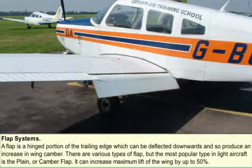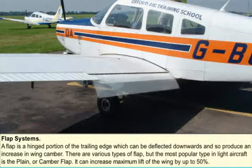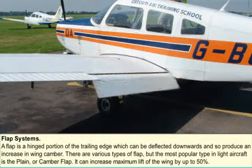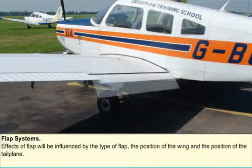The most popular type of flap used on light aircraft is the plane or camber flap. This type of flap increases the camber of the wing when extended, and in doing so can increase the maximum lift of the wing by about 50%. Lowering flap will increase both the lift and the drag of the aircraft, but not in the same proportion. Selecting flap will cause a pitch change. The overall change of pitch will be influenced by the type of flap, the position of the wing, and the position of the tailplane.